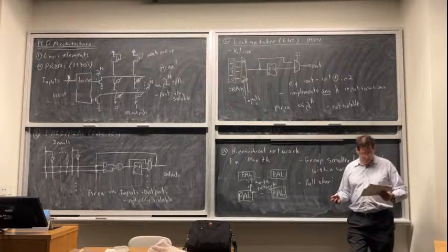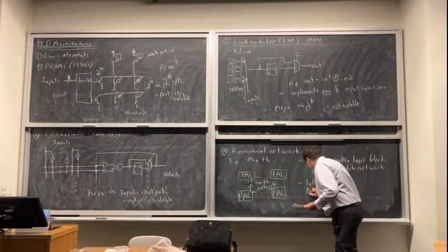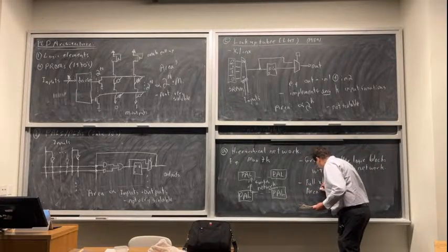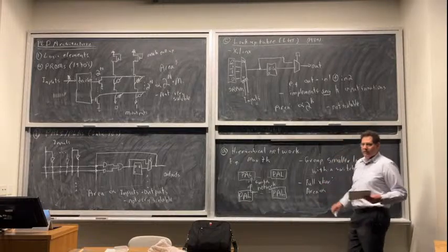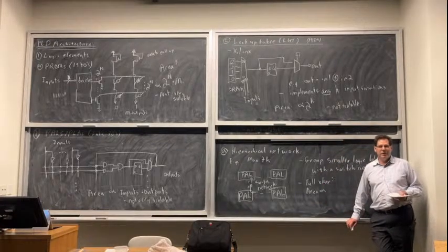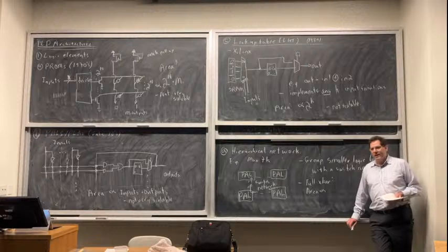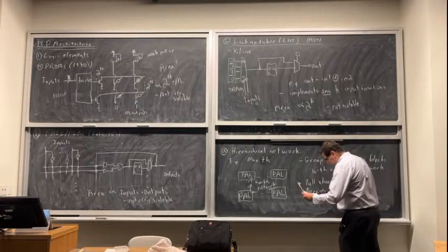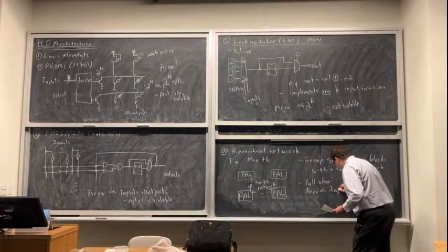But what is its area? How does the area of a crossbar grow? Any idea? There are a couple different ways you can build these, but they both grow with the same area asymptote. Yeah, it's n squared. Basically, they grow as inputs times outputs, which if they're both n would be n squared.